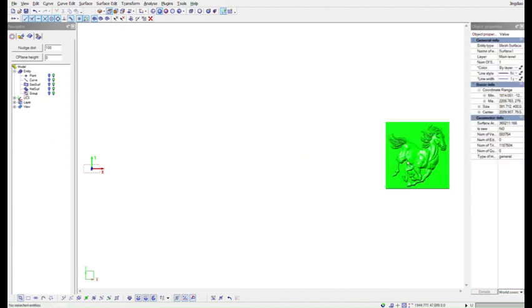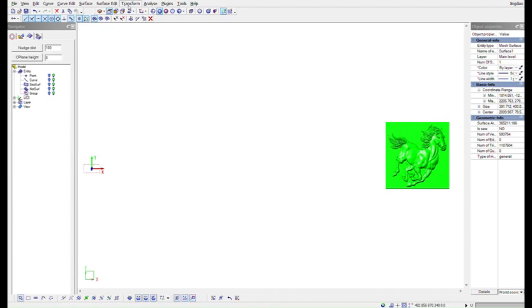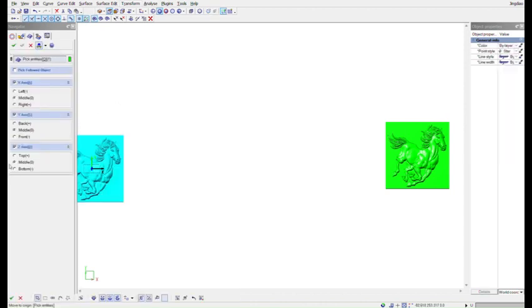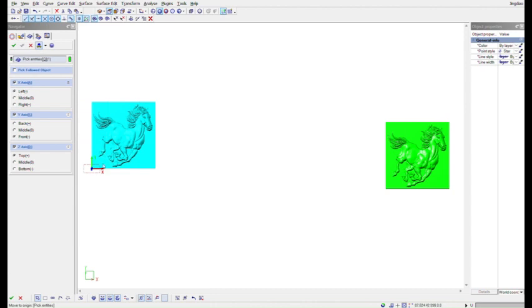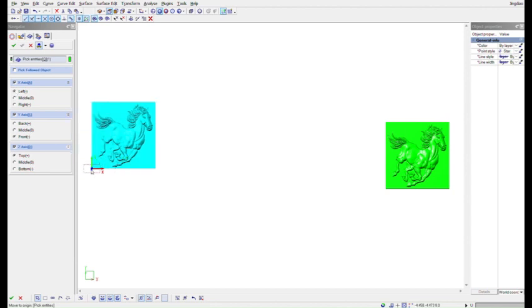Then you need to move the coordinates. You have to set the coordinates here. So select this model and choose move to origin. You have to move it to the 0 0 coordinates first. I will select top, front, left. You can select middle or anything, it is your preference. I will select top, front and left. Then it will come to the 0 0 position here, and okay.